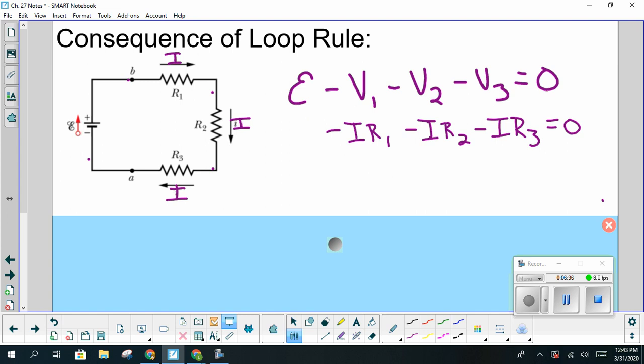So for our total circuit, so think of this as the EMF for the whole circuit, right? This is our EMF for the whole circuit. We can rewrite that as our current times the resistance for the whole circuit. Now, you could either write here EQ, equivalent, or you could write S for series. I'm going to write S for series right now, just because we have a simple series circuit.